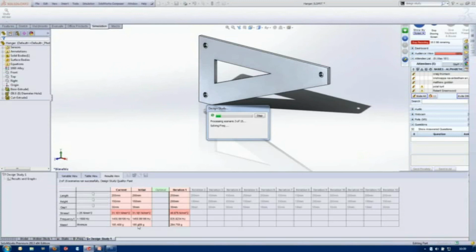And then once it's finished solving all of our iterations, it will pick the values that get us the best result on our goal, which is the last row, while passing both our stress and our frequency test in the constraints area. So this, unfortunately, it's not gonna finish, which is a real shame because I'd like to have shown you those results. I tell you what, it was a lot quicker than I was testing yesterday.